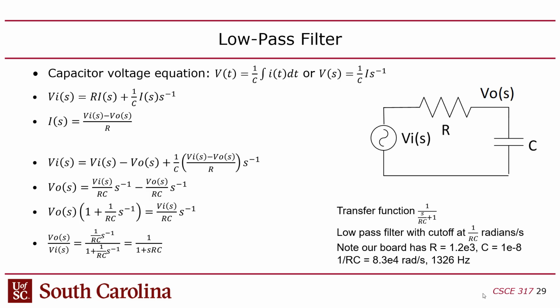That's your goal. The problem is that Alex found out the hard way that if you do that, you end up with the PWM, which is like a square wave. I mentioned the step function has an infinite number of frequencies in it, right? Now the PWM signal coming from the chip, the ESP32, is not a perfect square wave because it doesn't have an infinite slope. A square wave has an infinite slope.